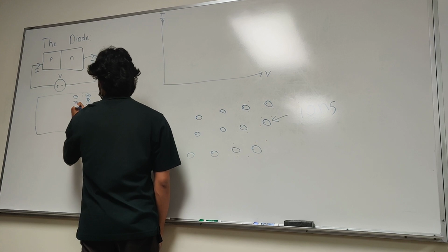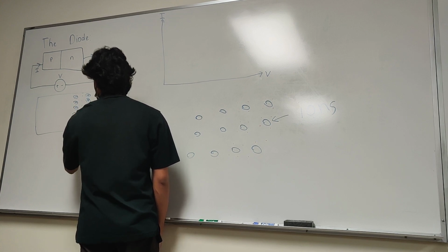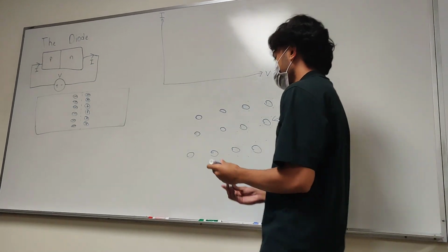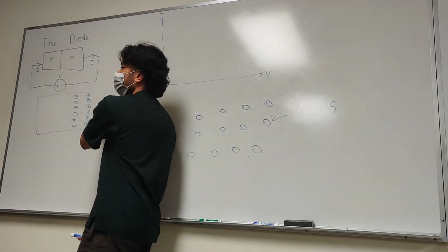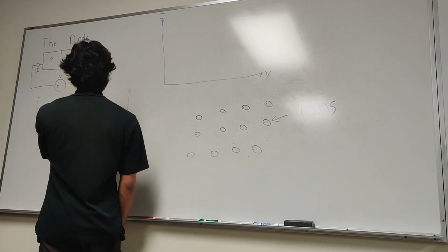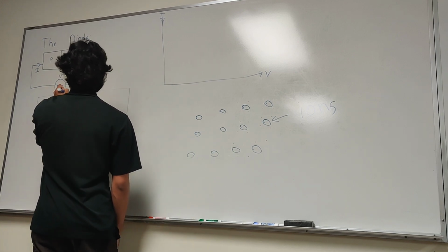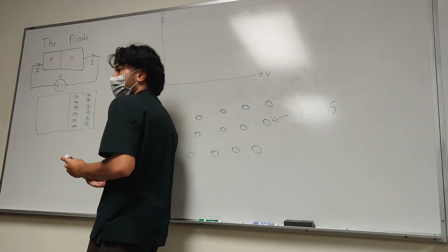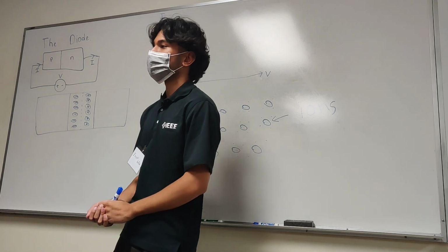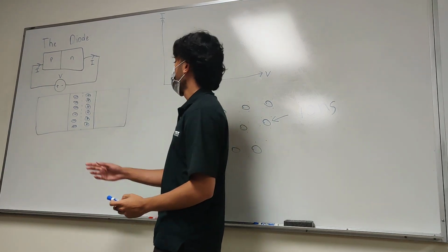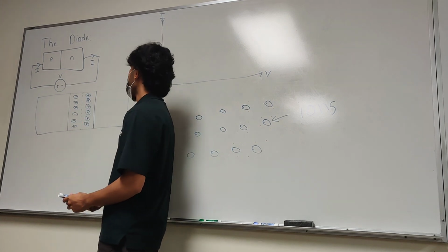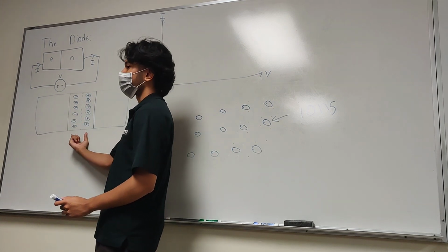These ions are these things here. Okay? So these charges, they're sitting here. They can't move. They're part of the crystal. What happens is as we bring these 2 pieces of semiconductor closer together, these free particles, these holes and electrons that are free to move around, we refer to these as charge carriers, they're going to move away from this plane of contact. So what happens is we're now left with these ions.